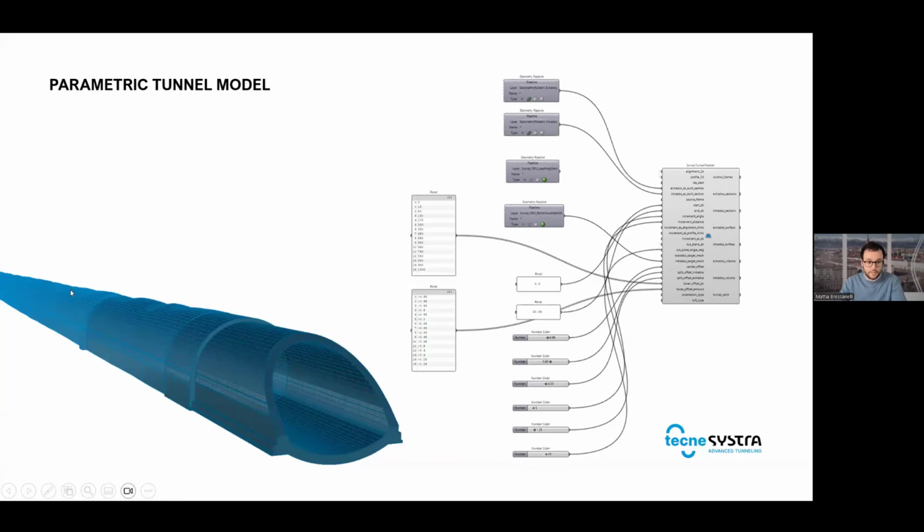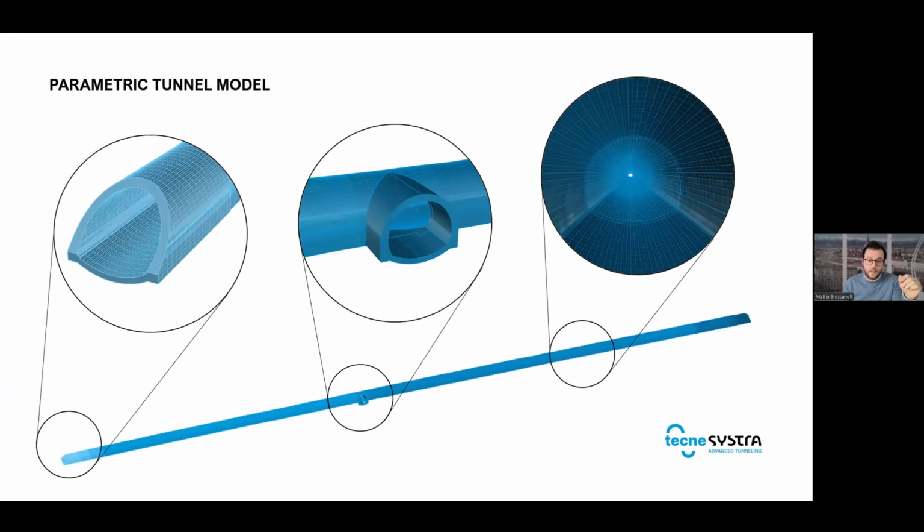here at the top, you see the extrados is kind of wavy because it's following that regression surface from the extrados, and for the intrados you would see the same thing, and we will see that in detail when we see the demo part. I will cut a section through and I will show you that it's actually snapping to the intrados mesh and to the extrados as well. And then we can model different sections of the tunnel.